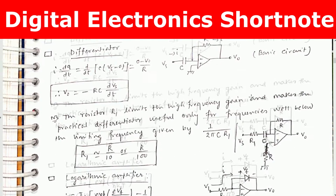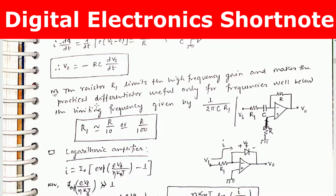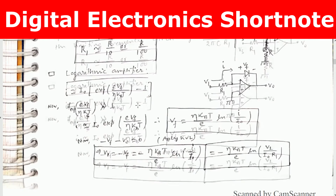This is the basic circuit, but in practice we see some modification. A resistance R1 along with this resistance R is employed. The resistance R1 is approximately R by 10 or R by 100. This resistance R1 limits the high frequency gain and makes the practical differentiator useful only for frequencies well below the limiting frequency, which is given by 1 by 2 pi C into R1. And this is the practical differentiator circuit.